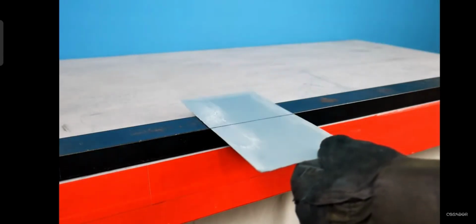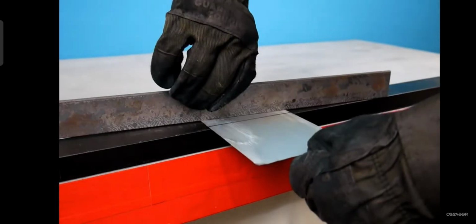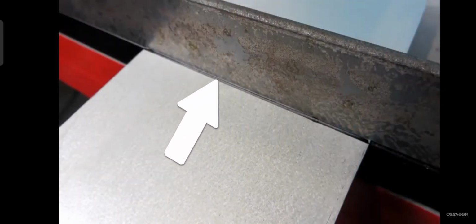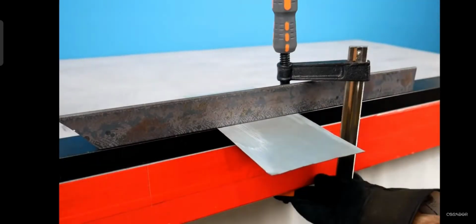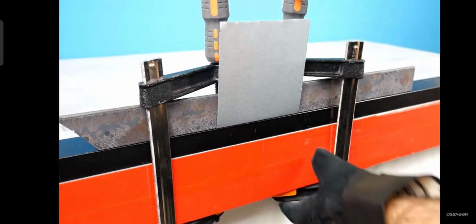Because each of the methods are based on force, I need to clamp this well. I sandwich the steel sheet between a rectangular tube and rigid angle, which are both longer than the sheet that I wish to bend, at the same time lining up the edge of my markings. I make sure that the two clamps are over the steel sheet but not interfering with the direction of the bend. Okay, let's start bending some metal.